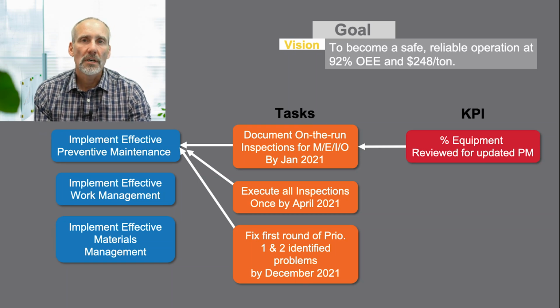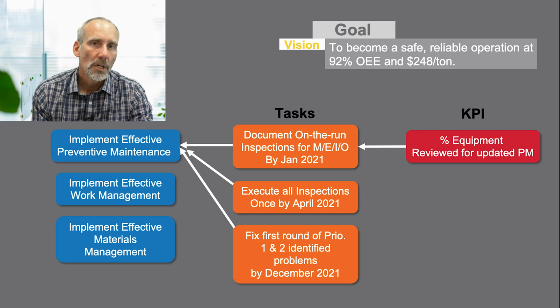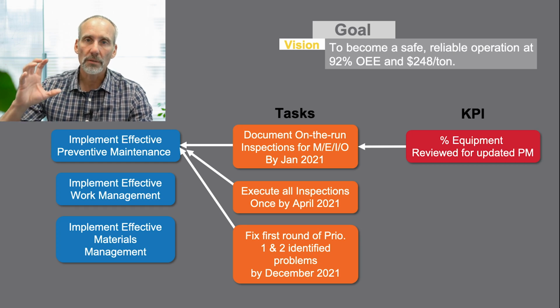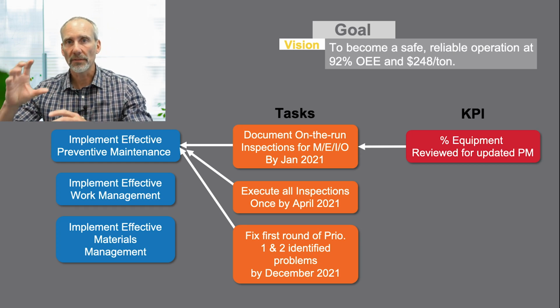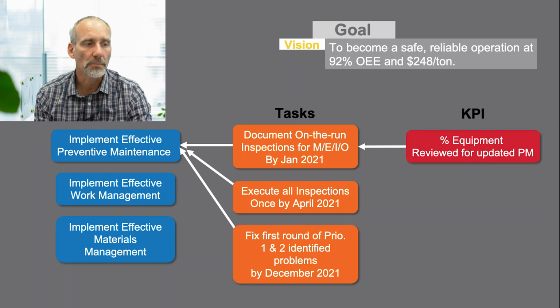And when we do it here at IDCON, we're trying to really get down to something that is tangible for the person. So for example, to improve reliability overall is a very fuzzy goal. But if you say to electricians, we want you to try to increase motor life, we're going to take a measurement and we're going to measure how many motors we change out every year, and then see how many motors we have total. So if you take the total number of motors, divide it by how many we change out. We have 1,000 motors in the plant, we change out 100. Well, you take 1,000 divided by 100 and you get 10 years average life. I know it's not an exact number, but if you trend that, it actually is a pretty decent measurement.